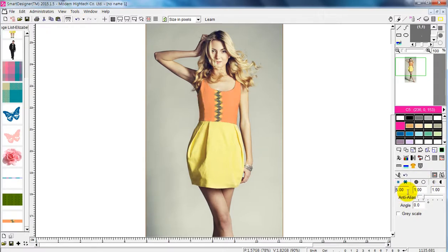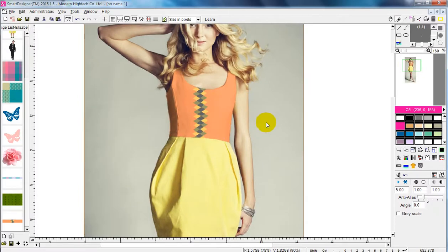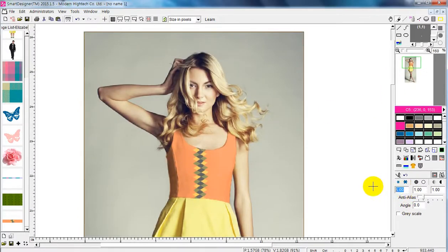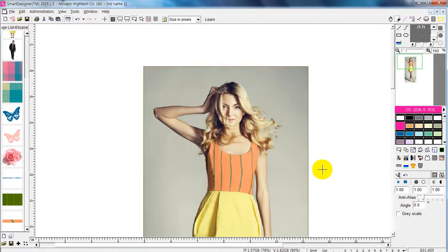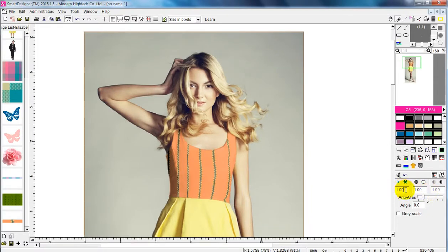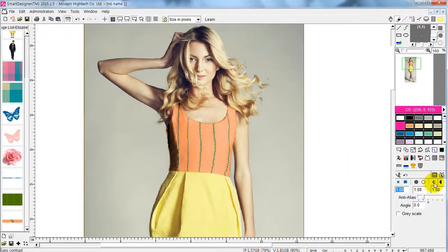Using this one, you can set the sizes of the pattern like I mentioned a while ago. That's why I said the define dimension function is not really that important, because you can actually change the size of the pattern from here anyway. So if you wanted 7, or if you wanted little stripes, you can make it 2, or even smaller stripes, you can make it 1. The brightness of the whole portion, shadowing to make it look more realistic, you can all adjust it here.